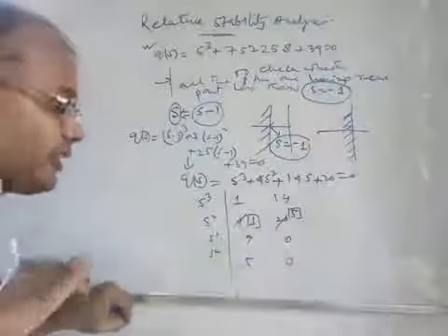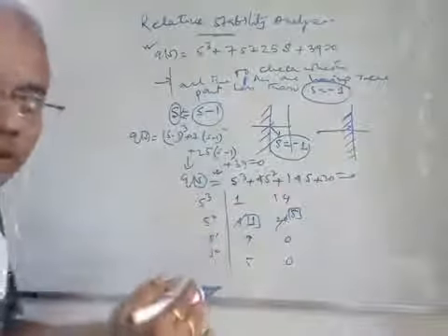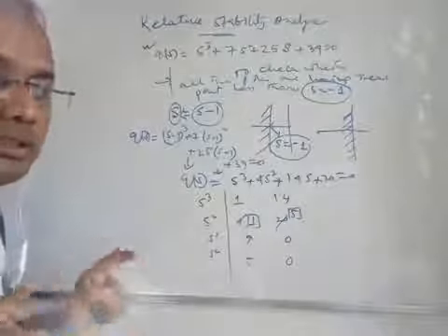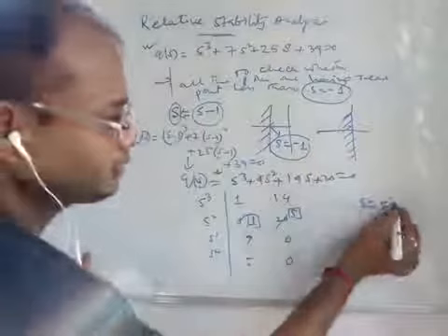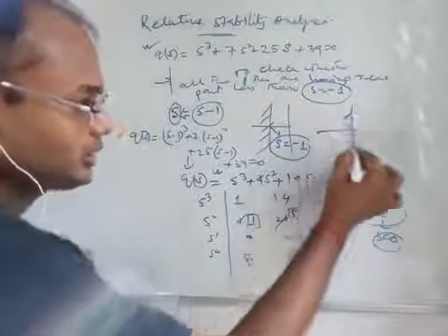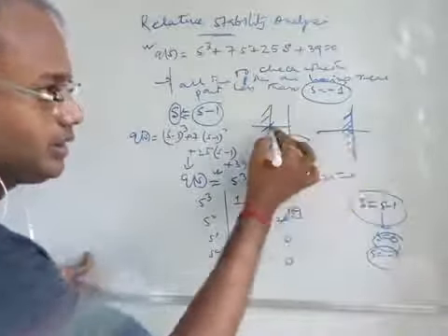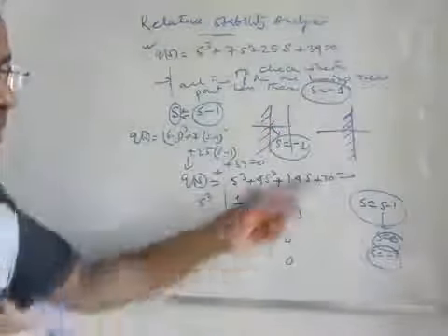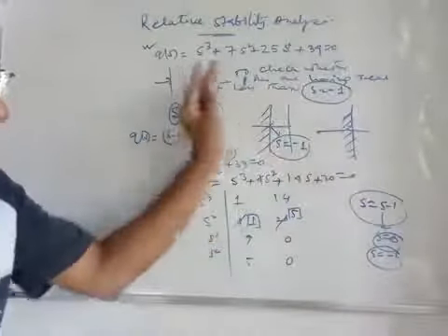So what you see, for this polynomial, which has been shifted by using the expression of the s plane, s is equal to s minus 1, not s is equal to s. So once s is equal to s minus 1, you see what happens. In the original case, if the value of s is equal to 0, that means this is shifted to s is equal to minus 1. That means this position is shifted to this position. So the imaginary axis was at s is equal to 0, and here you have shifted the complete plane to these positions.